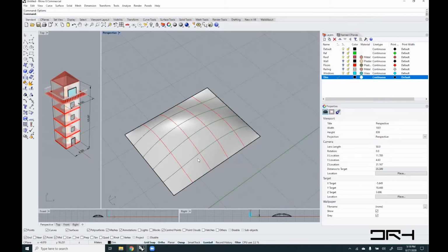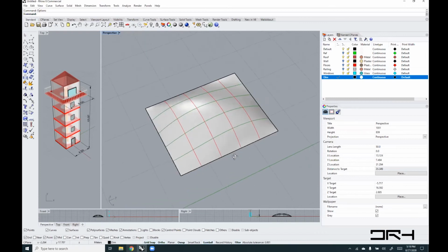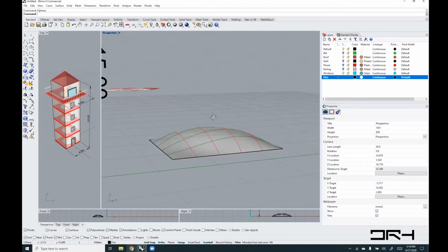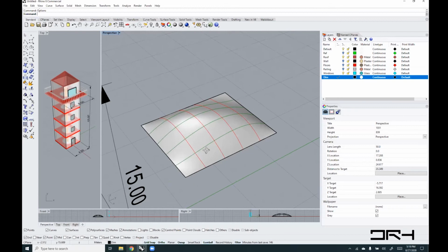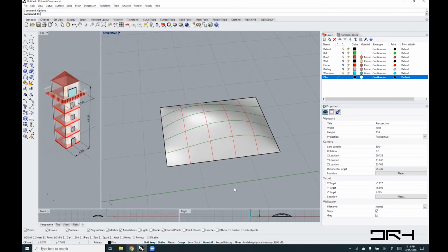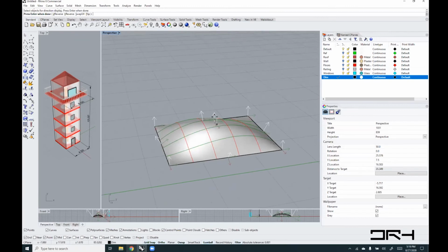And from that point on, any surface you create, the ISO curves are going to be colored with the colors that you specified. There's another really nice setting if you want to know where the normal or the up direction of your surface is. Each surface has a front and a back. And right now I wouldn't know which direction unless I run the direction command again, click on my surface, and then it shows me, the white is where the up direction of my surface is. There is a way to visually tell.